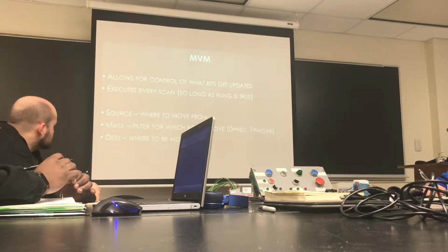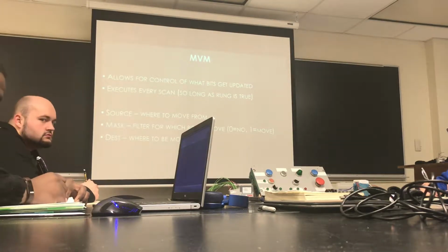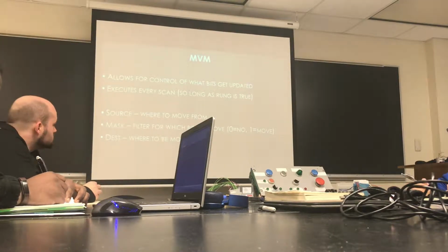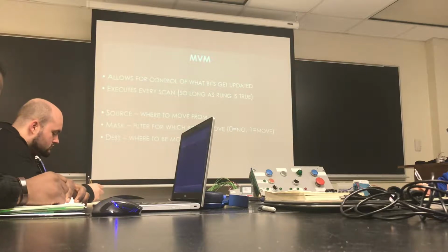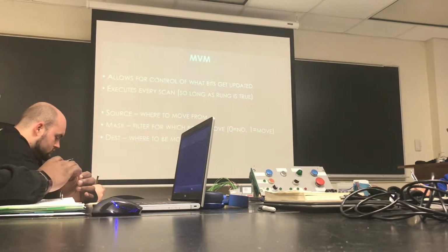It does execute every time, through every scan. And so as long as that rung is true, it's doing the move. And so sometimes you have to be careful because it could be changing stuff before you're ready for it to be changed. And imagine a box coming down the conveyor, you need to go pick it up. And you say, the box is here, you go to grab it, but it's now here, right? And you miss it.